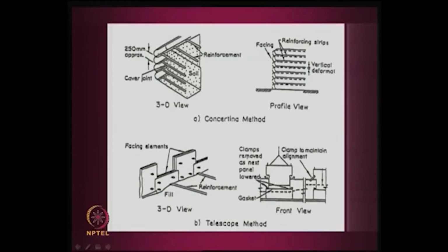So, that 15 is more than the 10 required, so it is fine. That is how we have to do the design, and once you are able to design at every step in some simple sense, then of course, there is a lot of sophistication involved, but in principle you must be able to design all the spacing and all the reinforcement like this, and I mean the spacing of the reinforcement.